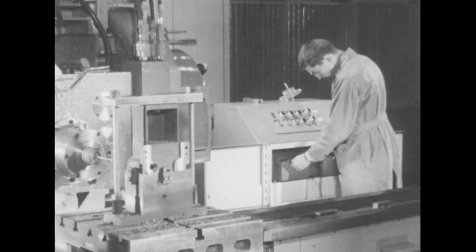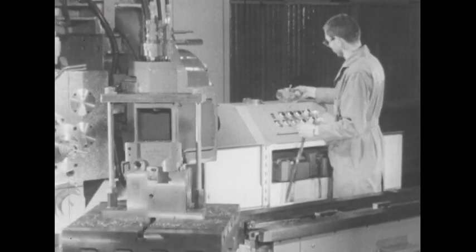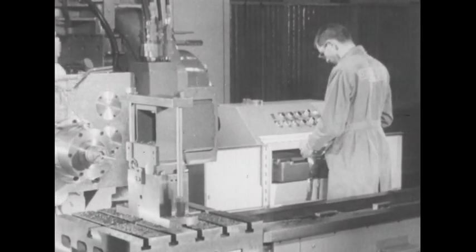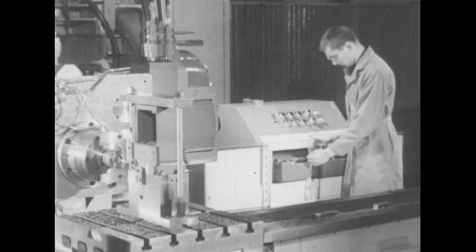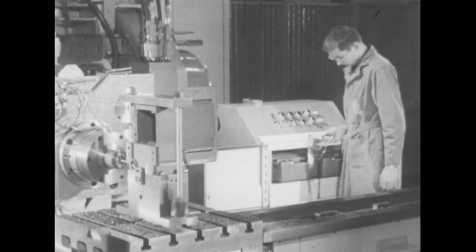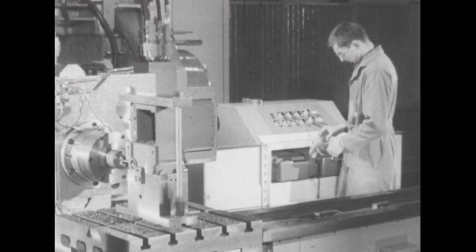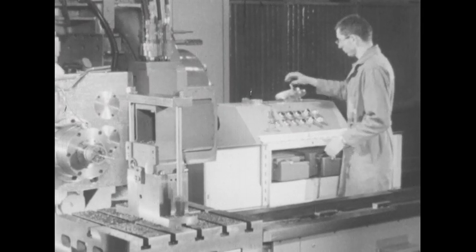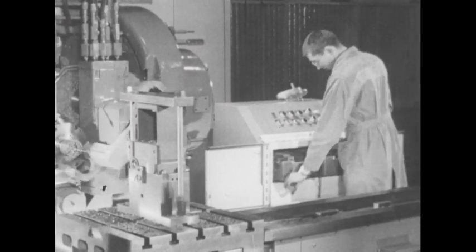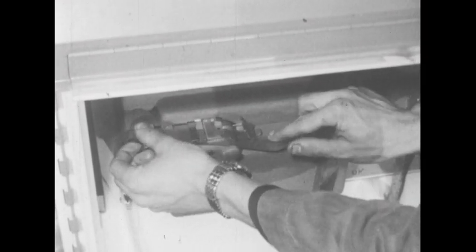Milwaukee-Matic is equipped with a built-in memory circuit which stores the information transmitted from the tape. All necessary items pertaining to each operation, such as location, tool change, speed, feed, and coolant, are automatically actuated and executed in the correct sequence and at the proper time. Upon completion of the setup work, the labor cost of machining each part using the Milwaukee-Matic concept is considerably less than that of conventional methods.